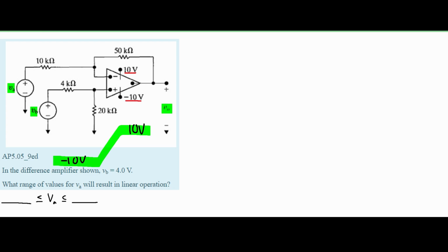So when I'm looking at this, I see the node voltage method. I'm going to have this as our first node, and the voltage for this is going to be our Vn for negative, because we have a negative right here. And since we know our op amp is inverted, we are going to have some negative feedback from our output that goes back into our op amp. We have to keep that in mind when we're doing the node voltage method.